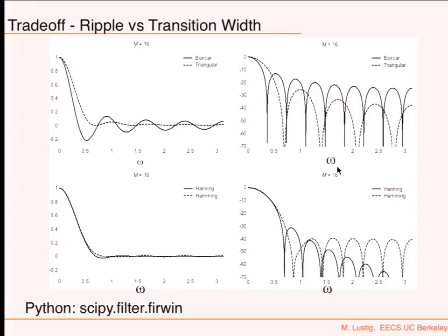Okay? And Python has scipy.signal.firwin. This is a function that uses exactly this window approach in order to design a filter. MATLAB has fir1, I think. Right, fir1. I think that's the filter design function that uses a window. Okay, that's the function that generates it using a window.